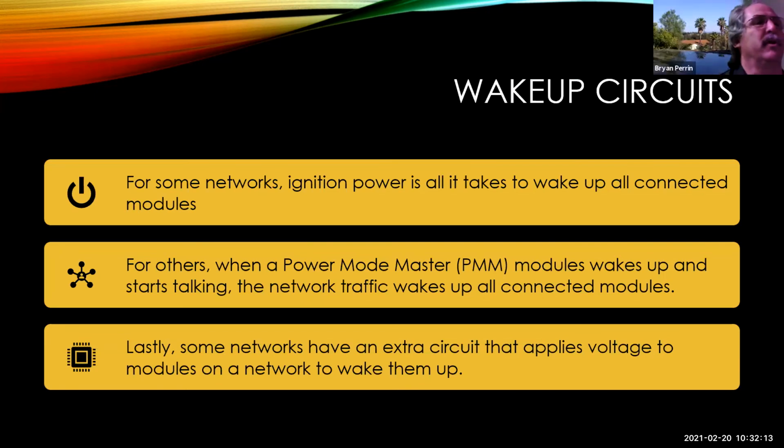So wake up circuits. I mentioned this a little bit earlier. For some networks, ignition power is all it takes to wake everybody up. Time to go to work. For others, there's a power mode master module which wakes up and starts talking. The network traffic wakes up all the connected modules.